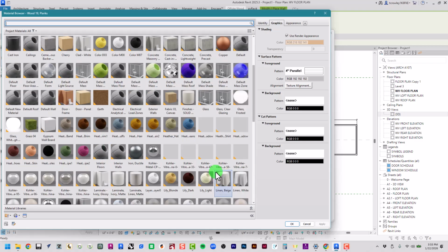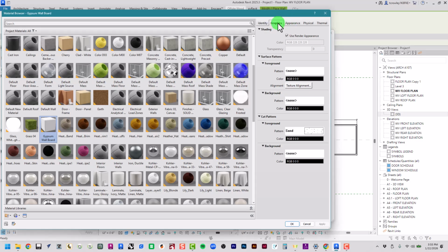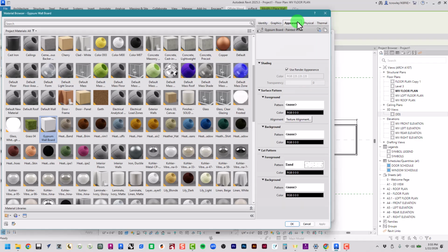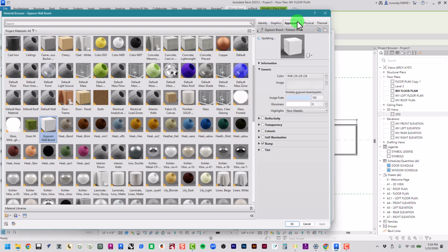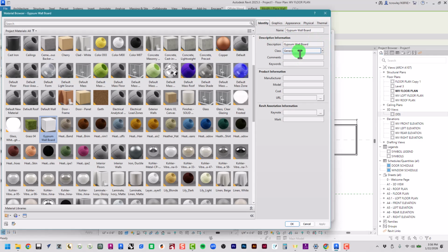If we were at an interiors or finishes manufacturing plant showcasing different materials, I can create a brand new material here in Revit and give it that specific name. I can add a couple of pieces of information that I might know about that material, such as the URL and how much that specific material costs. And all this juicy information is taken into Revit, and we can extract a lot of it through schedules and reports. That is way above this class.